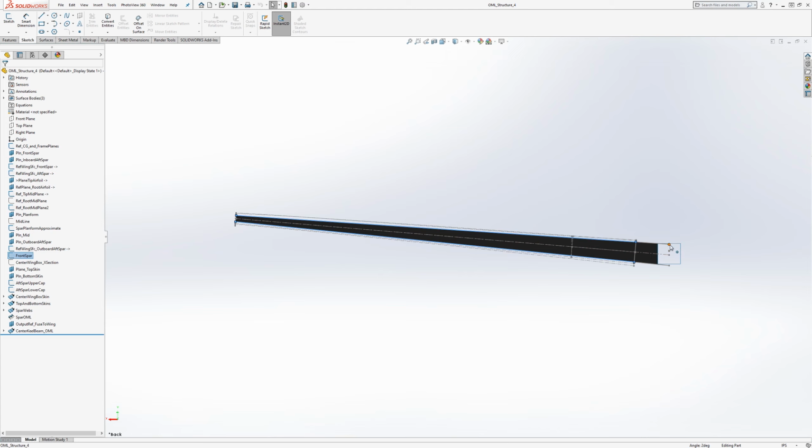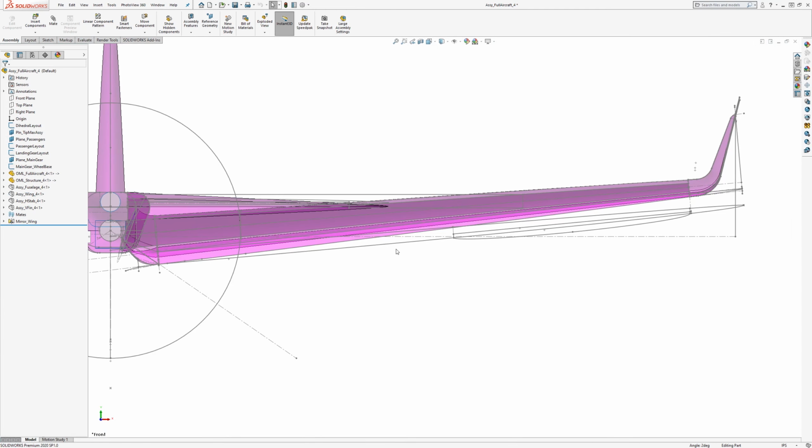So it continuously converges as a tapered beam. What that would mean for the root is just to set that angle initially, and then the spar caps can just be straight the entire length, which is easier to manufacture.